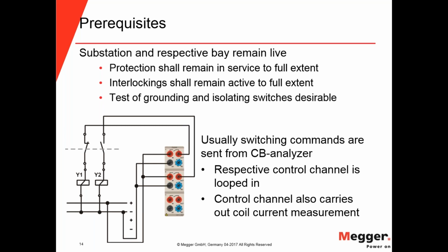The circuit breaker analyzer sends out the closing and open commands to your coils, and the channels also measure control voltage and coil current.